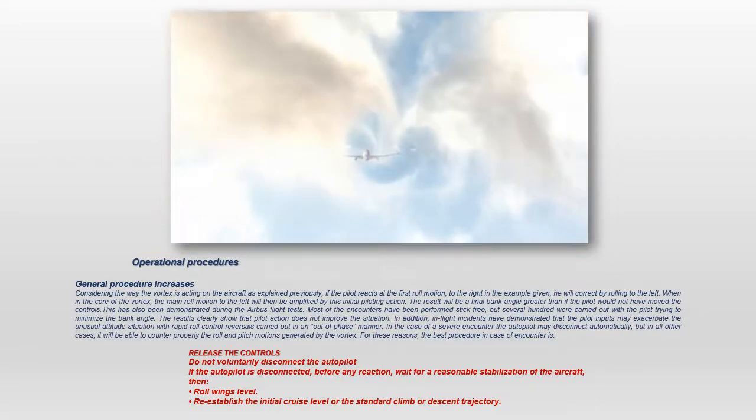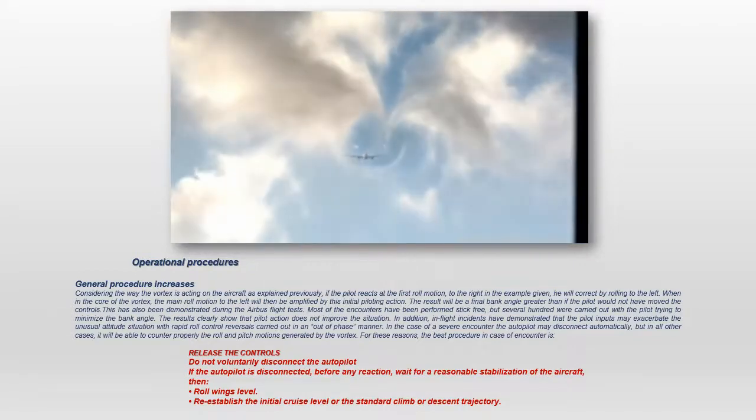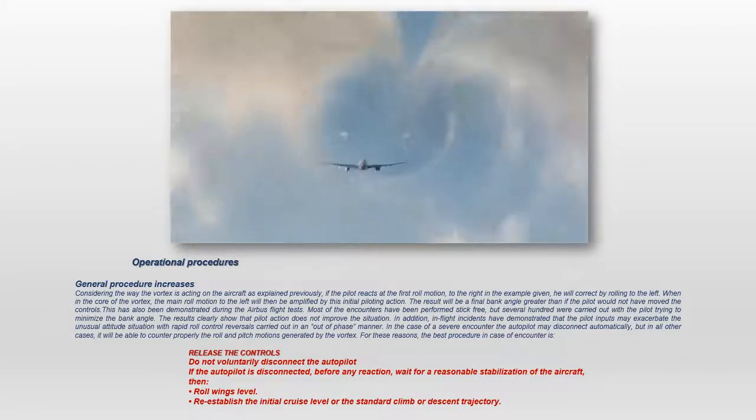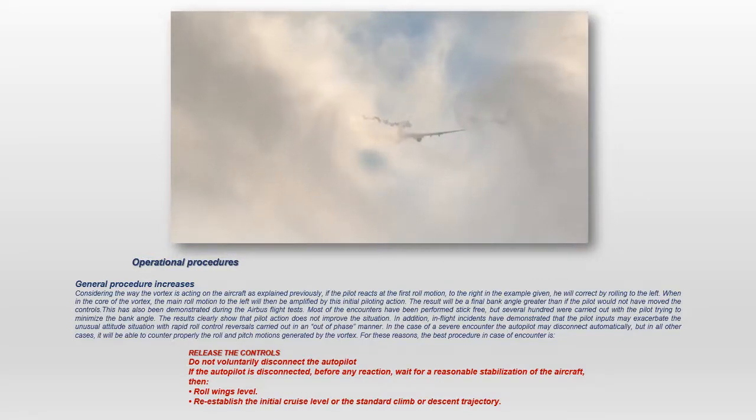This has also been demonstrated during the Airbus flight tests. Most of the encounters have been performed stick-free, but several hundred were carried out with the pilot trying to minimize the bank angle. The results clearly show that pilot action does not improve the situation. In addition, in-flight incidents have demonstrated that the pilot inputs may exacerbate the unusual attitude situation with rapid roll control reversals carried out in an out-of-phase manner.